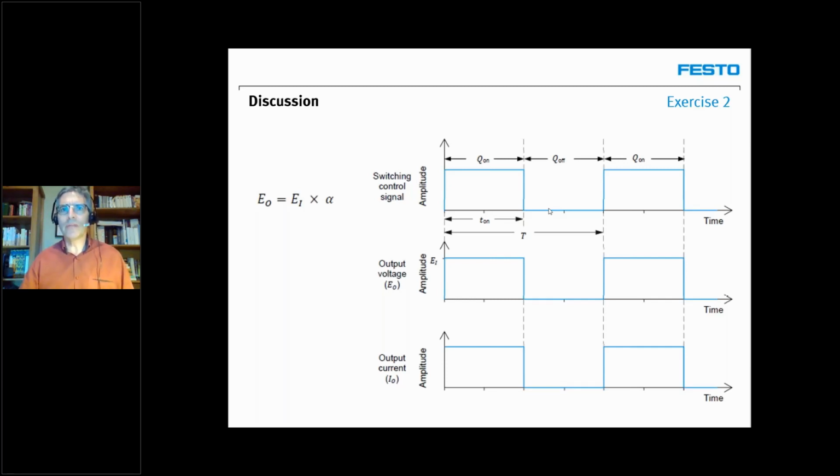A good example of that is a heating element in your house for baseboards or for your water heater or in your oven. We could control the amount of power that we send to such a heating element by using power electronics like that. We don't use power electronics in home appliances like that. It's done on a longer period, but let's say that would be a good example of where we could use power electronics like that to control the average power we send to the load.